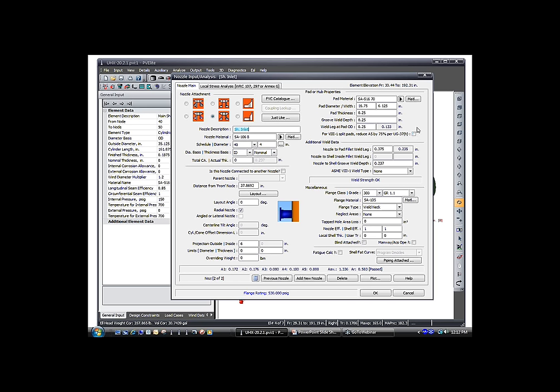Okay, so again, if your pad doesn't meet the requirements, then you need to check the box, and you'll notice down here on area 5, right here we have a current value of 0.888 square inches in this case. And if I check the box right here, notice that I have my 75% reduction.